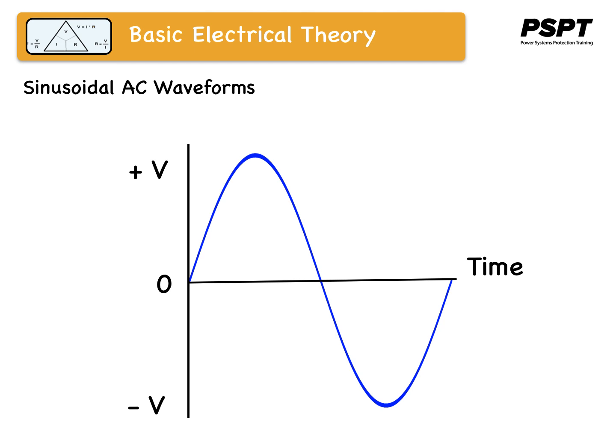In the voltage plot from an electromechanical alternator or generator, the change from one polarity to the other is a smooth one. The voltage level changes most rapidly at the crossover point and more slowly at the positive and negative peaks. Because this is a repetitive cycle, we describe the wave in terms of cycles, where one cycle is divided up into 360 parts or degrees.